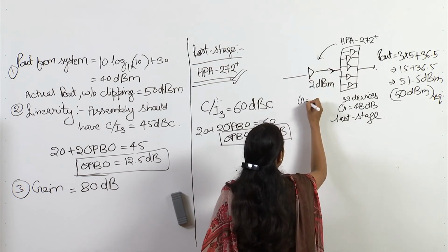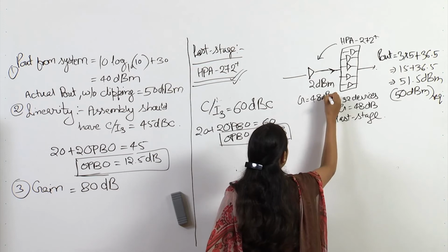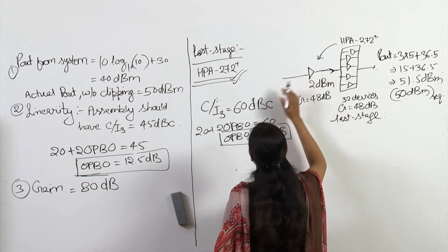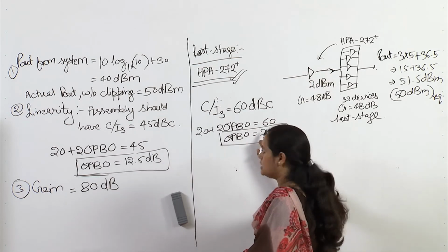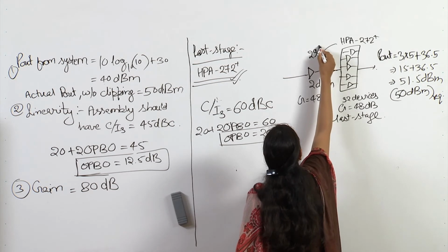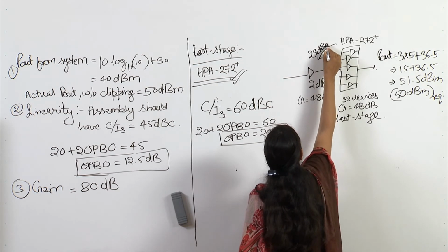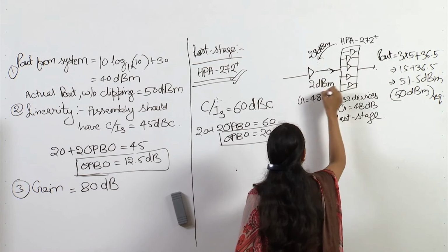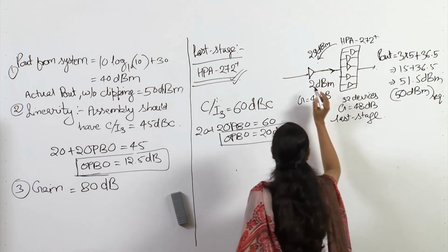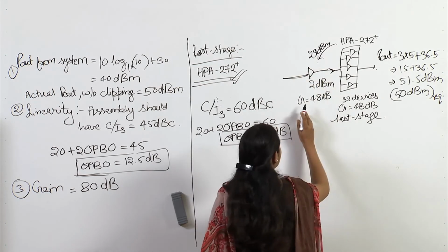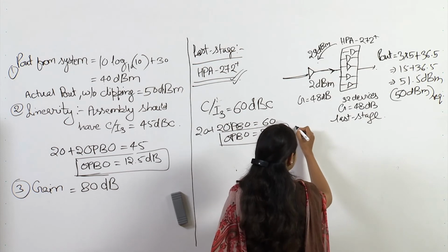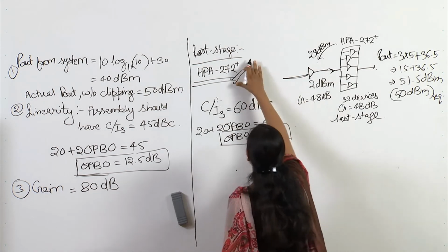The gain is again 48 dB, and it is providing 49 minus 20, so 29 dBm here, although we require 2 dBm, so we are well beyond our boundaries. So, it is good to have this here. So, it is a 2-stage amplifier basically with only this single device.